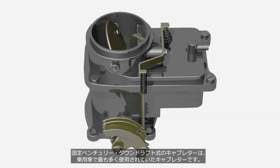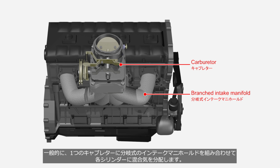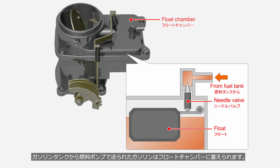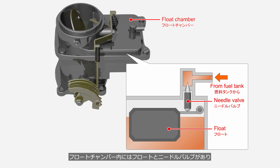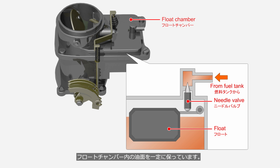The fixed venturi downdraft carburetor was the most commonly used type in passenger cars. Generally, a branched intake manifold is used with one carburetor to distribute the air-fuel mixture to each cylinder. Gasoline sent from the fuel tank by the fuel pump is stored in the float chamber. The float chamber is equipped with a float and a needle valve, which control the amount of gasoline flowing into the float chamber and maintain a constant fuel level within it. If the fuel level is not constant, it will affect the air-fuel ratio, leading to poor engine operation.